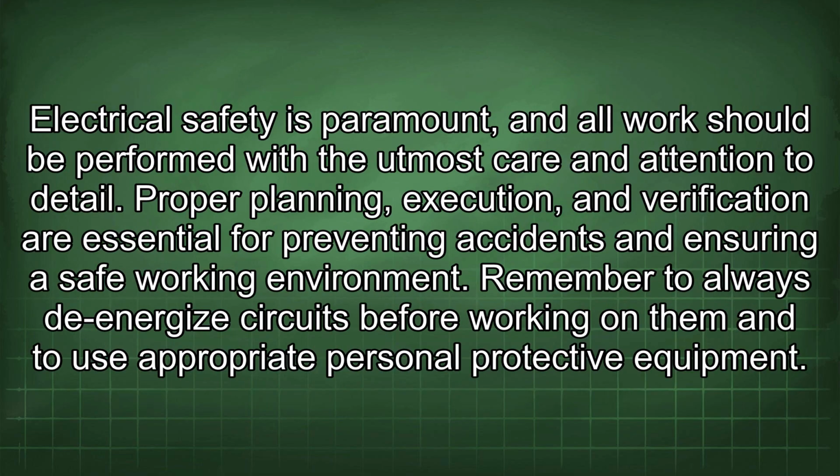Electrical safety is paramount, and all work should be performed with the utmost care and attention to detail. Proper planning, execution, and verification are essential for preventing accidents and ensuring a safe working environment. Remember to always de-energize circuits before working on them and to use appropriate personal protective equipment.